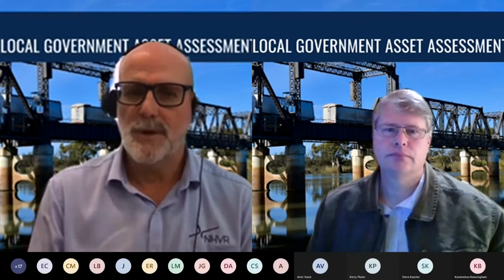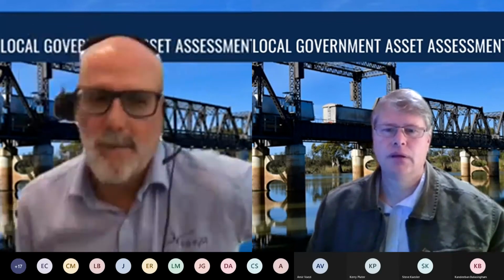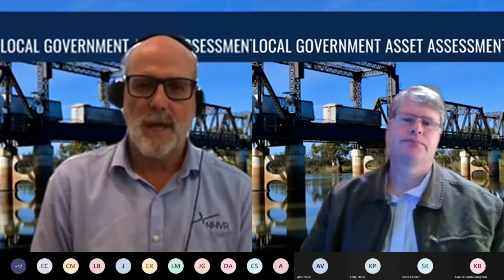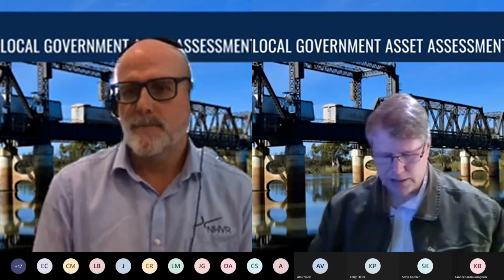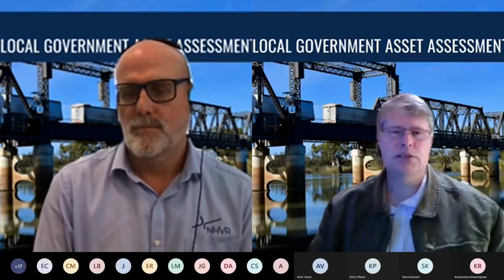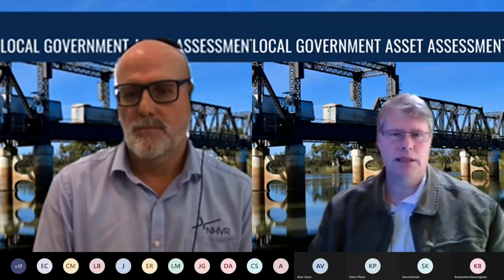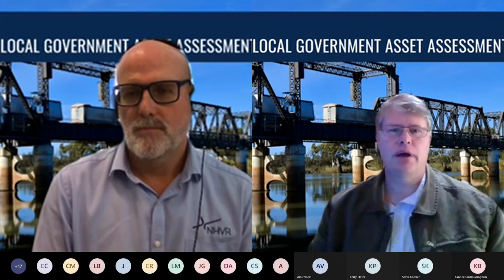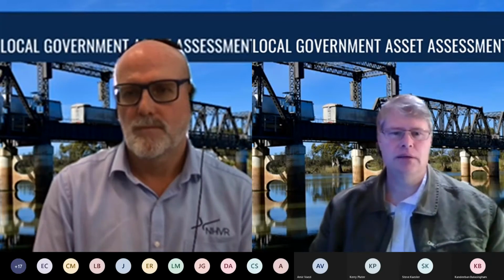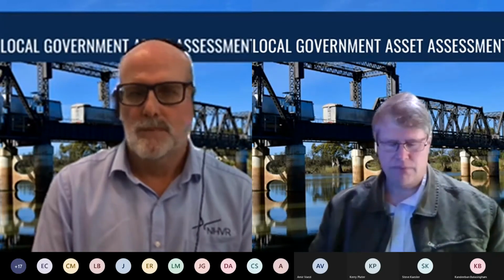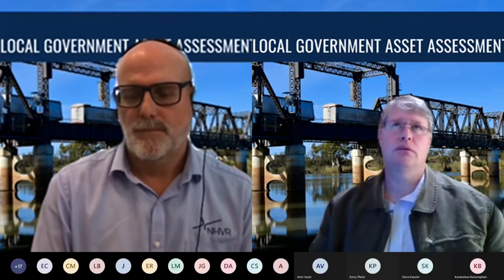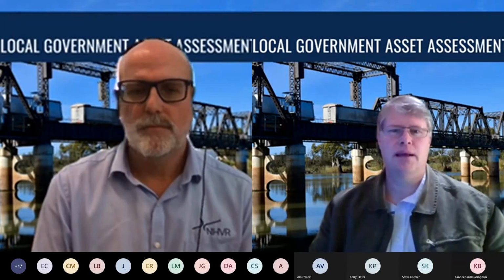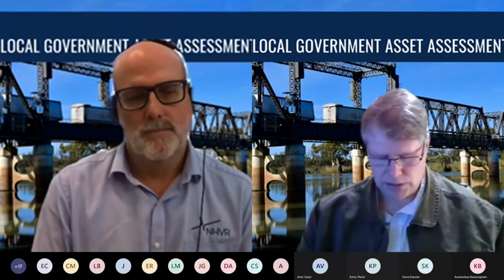And Les, what are the rules in AS 5100 Part 7 for assessing the impacts of multiple vehicles on a structure? I think we covered this in the previous webinar, Neil, where you looked at the associated lane factor. Yeah, that's right. The rules are basically that you can consider either design lanes or marked lanes, and for each of those lanes, you need to put a vehicle in it, and then for vehicles in subsequent lanes, you reduce the magnitude of that vehicle by a set amount. So 0.8 for the second lane, and then 0.4 for additional lanes.